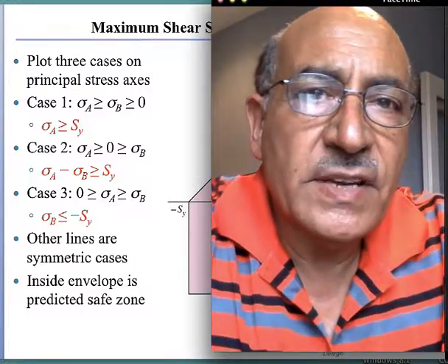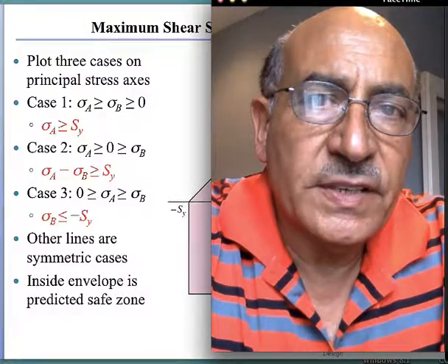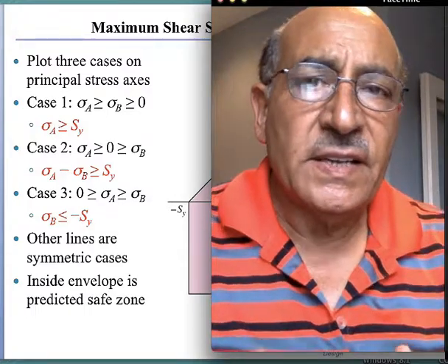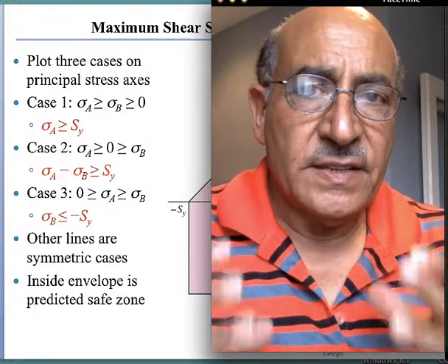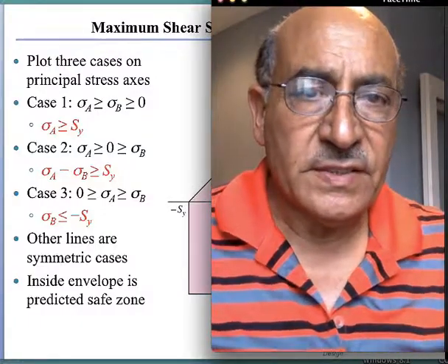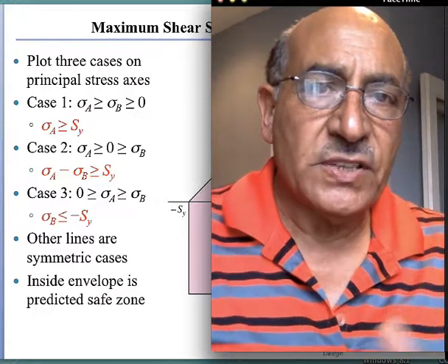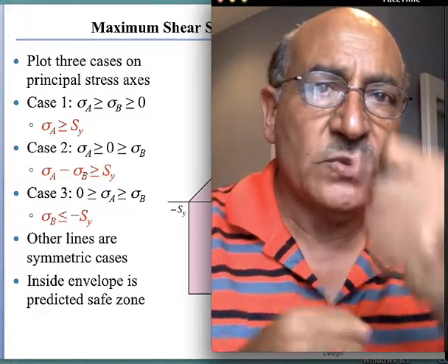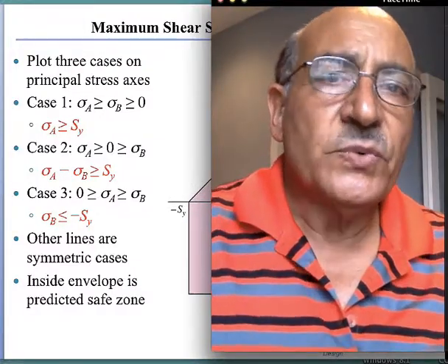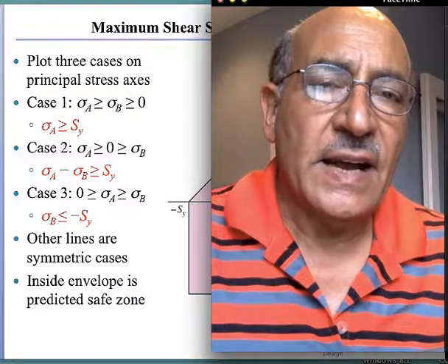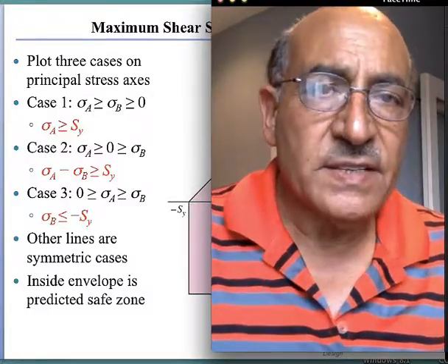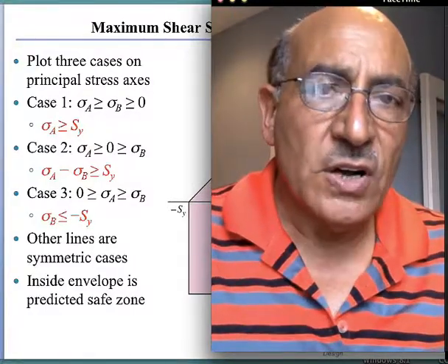Now what I would like to do is discuss a third theory, and that is based on this concept. Every material has a stress state, and the stresses can be divided into two parts. One part represents hydrostatic compression or tension, so the stresses are equal in the three different directions. And then on top of this, we would have deviations from this very highly symmetric system. And the deviations from this highly symmetric system are assumed to cause failure.